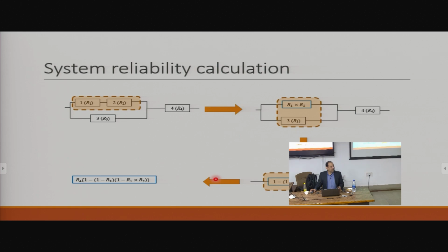Yeah, so we can envision many scenarios. Heat is one. If there's a power surge, or the flow rate is too high in the Venturi, or user error, it can cause cascading failures, right? And the other thing is that if one subsystem fails, which was in parallel, that increases the load in the other system, and that also fails. So component failures are not independent events more often than not, and that has to be built into our calculations, right?